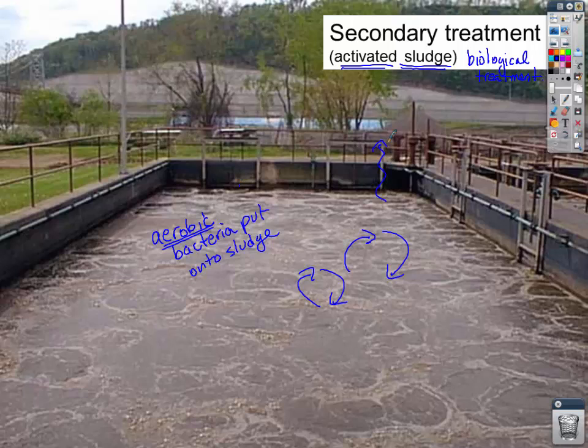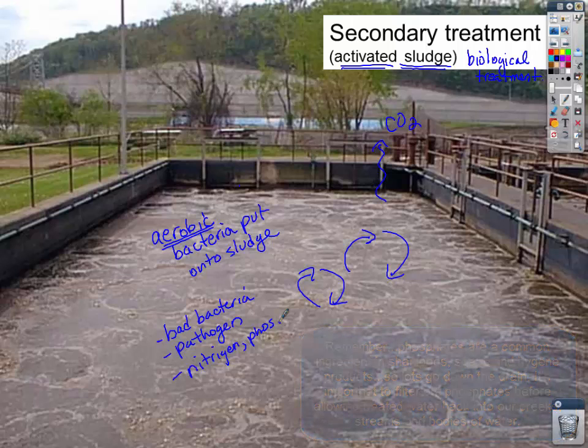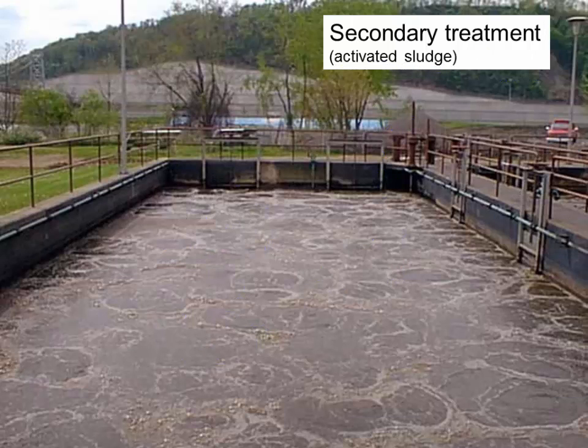The byproduct is carbon dioxide. That's the only byproduct. And what we're doing is we're trying to get rid of those bad bacterias, the pathogens, all right, the viruses. We're also in this step getting rid of all those nitrogens and phosphorus, those things that somewhere down the road are going to produce or result in eutrophication. We're getting those out of there here. All right. Now, secondary treatment is incredibly important, and along our path, that's doing all the biological process for us.